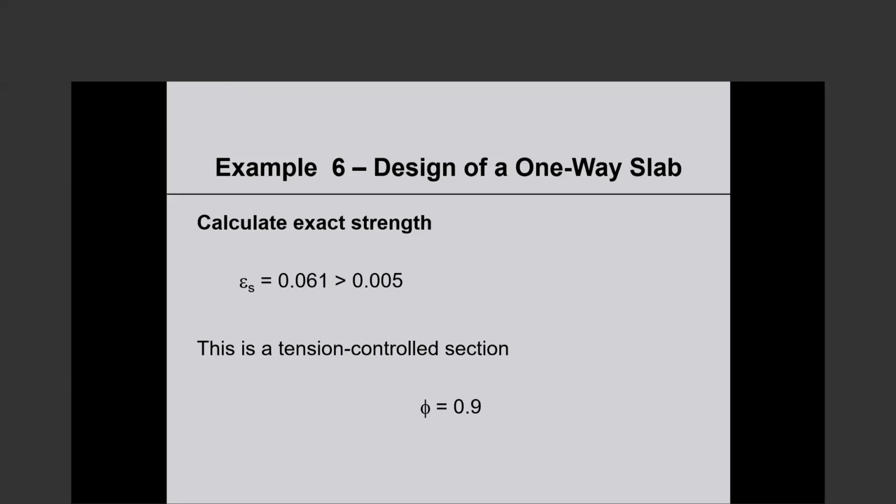I do not quite understand what the thinking is. So the slab in monolithic construction, part of the slab acts together with the beam. So your beam is the physical beam plus the overhanging flanges on the two sides, and this is not conditional.